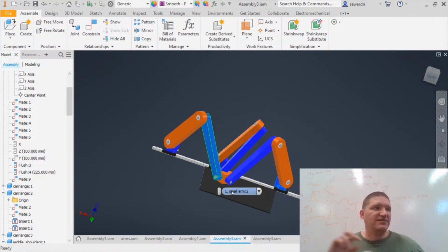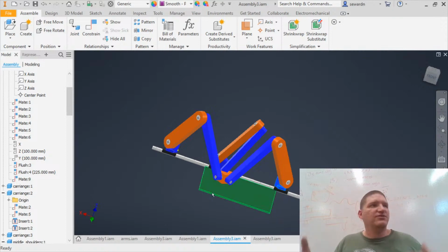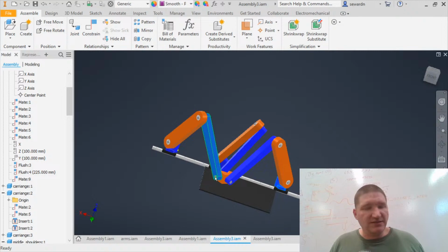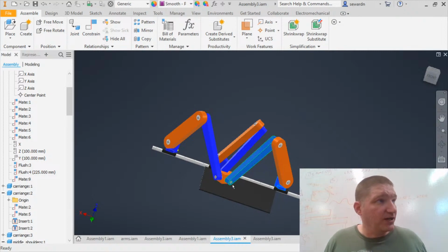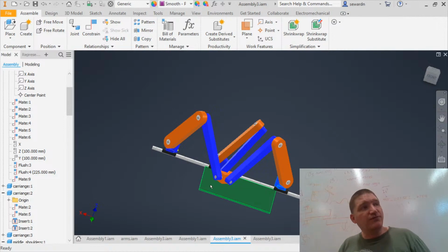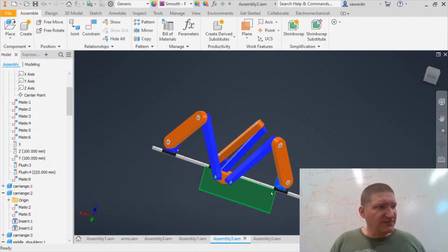There's a few different ways to do it, but basically you need U-joints here instead of revolute joints, and you could get the job done, or ball joints or something like this. So the constraint's going to be a little trickier. I'd have to think about that. I think U-joints, I don't think ball joints would work, but yeah, you could do curved rails. It makes the mechanism not quite as clean. Not as clean as I would want.